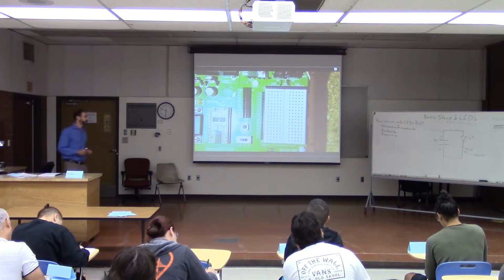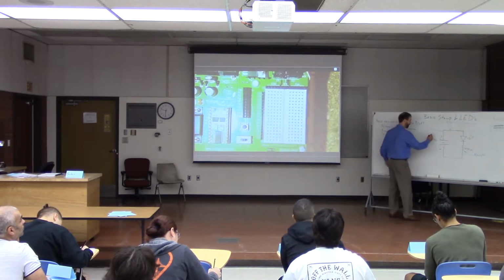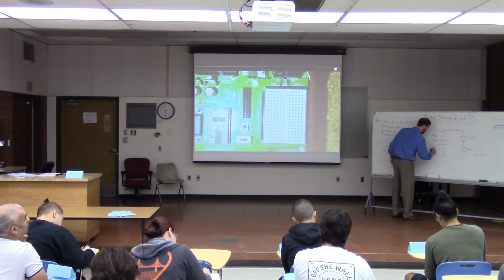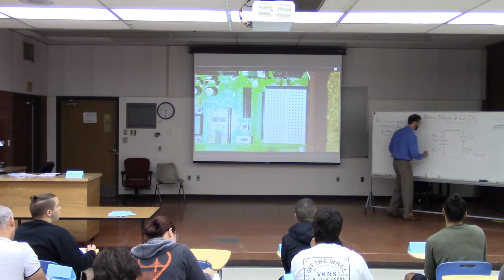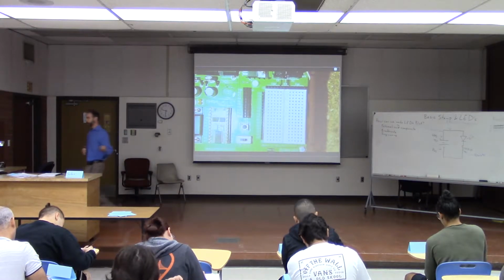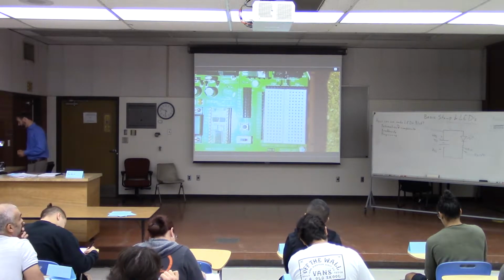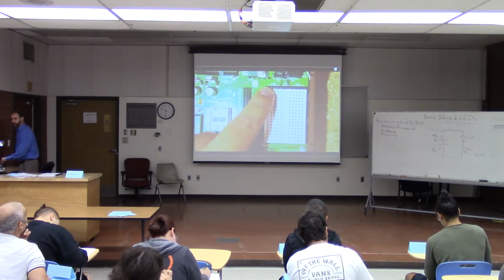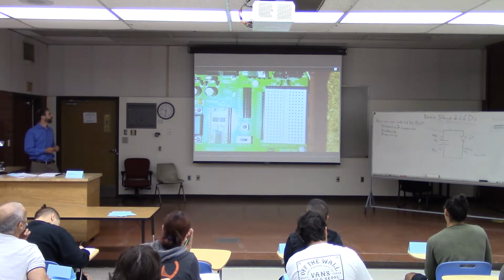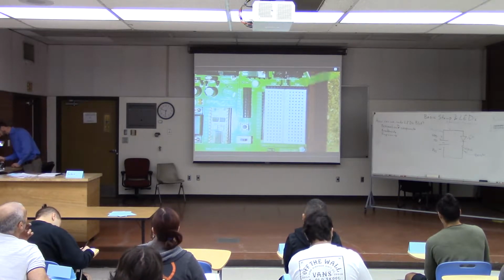The positive side of the power supply is also known as VDD. The negative side is also known as VSS. Okay. So I know that VDD has to be connected to the anode of the LED. So I look over here on my board and I find that there's VDD labeled on the top of that board. Okay. And if you look closely, you can see that VDD is right next to these